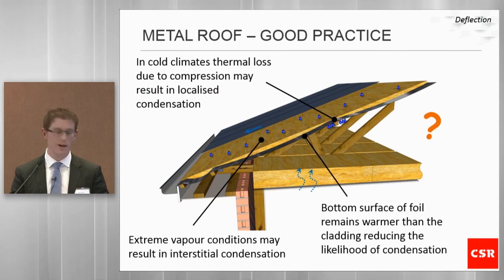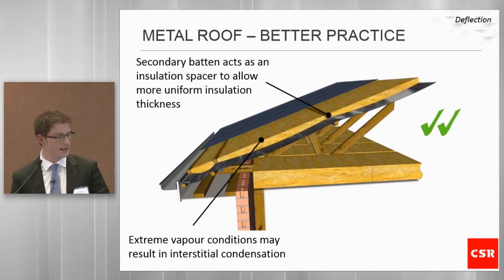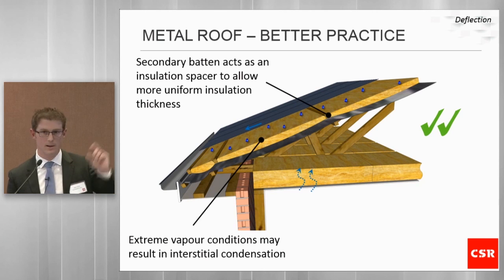Additionally, if you have higher temperatures, higher humidity on the inside of the building with extremely cold claddings, then that means you've got a very large vapour pressure pushing the water vapour out. And when it pushes up against the vapour barrier on the underside of that foil face blanket, we know that it's very hard in practice to get a perfect vapor barrier. For the overlaps, potential damage to the membrane during install, all these things could potentially allow water vapor to get into the blanket. So over time, potentially accumulation of moisture. We are investigating approaches to start to enhance this system, which would incorporate a spacer over the top.